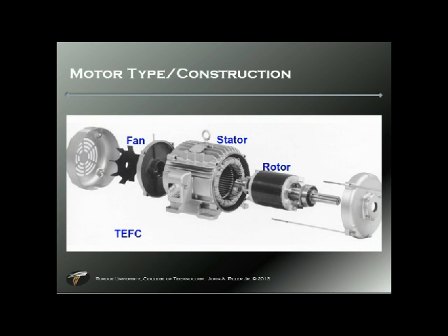All right, so here's an exploded drawing of the induction motor. This would be the totally enclosed fan cooled. So the very back on the left there is the finger safe guard for the fan. There's a fan paddle wheel to blow air across the fins of the motor on the stator. The stator is the central point that has the mounting. That in an induction motor is the armature, right? There's current applied to the stator. The rotor itself is there in the center.